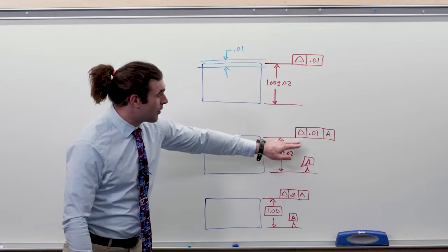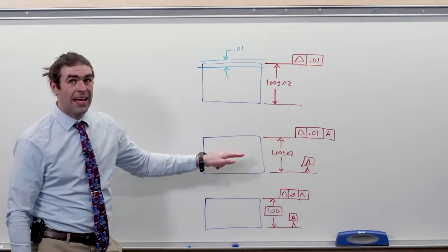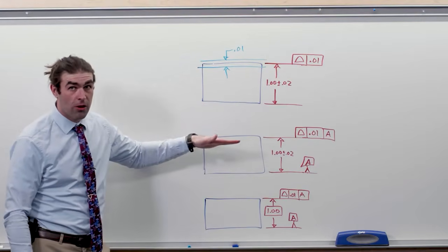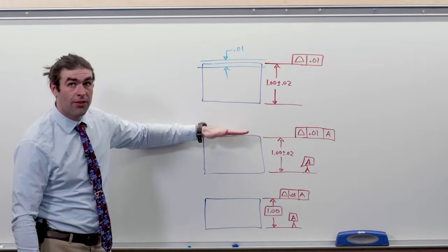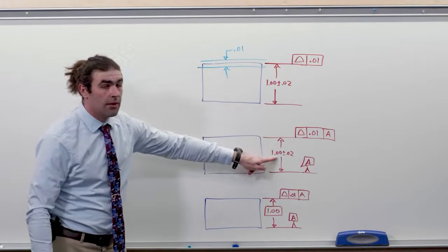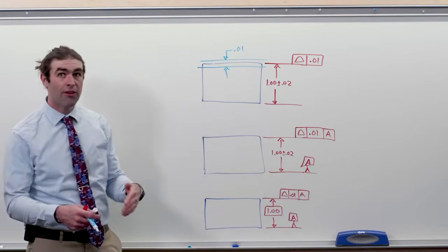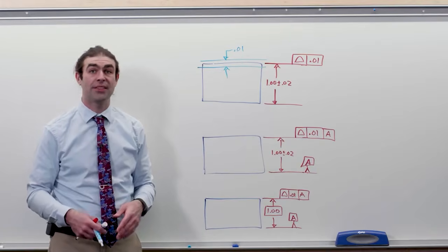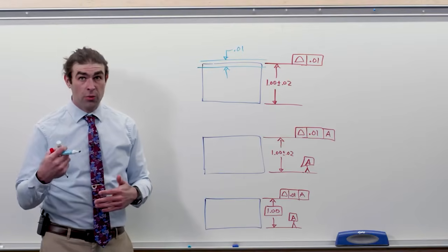So what this does, we've got a 10 thousandths tolerance zone to A. So that's essentially a parallelism callout. That tolerance zone needs to be parallel to A, but it's located with this larger plus or minus dimension. So this is essentially profile masquerading as a parallelism tolerance. Again, you really shouldn't do this.